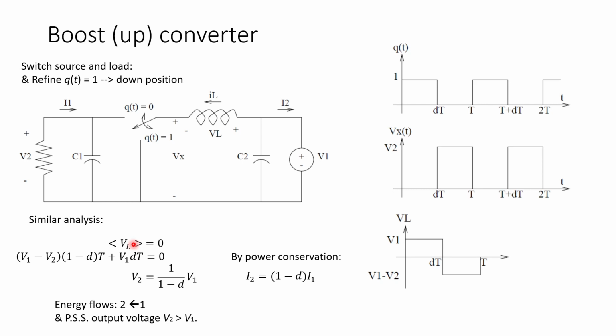Okay, and for the process to get to this formulation, to get the expanded form of this average voltage equal to 0, how do you get this? You just need to draw the graph of the voltage of the inductor in the case of switching on and in the case of switching off. Then you can find the average value. Finally, you get the relationship between V2 and V1.